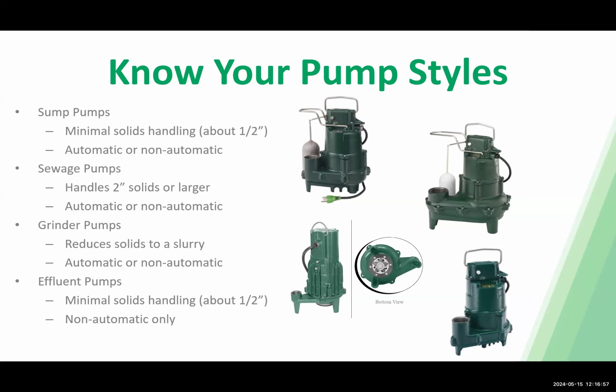Typically, I would say try to avoid putting any kind of grease down a sink. No pump really likes having grease go through them. No system really likes it either. Float switches can get clogged with them as well.